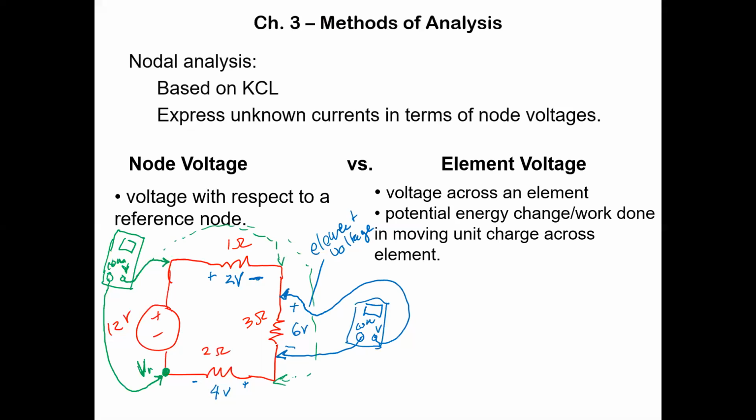We're going to call those node voltages. They give us the voltage, the potential difference, between any point on that circuit relative to our VR node. Our VR node, which is our reference node, is assumed to be 0 volts. It's the reference node, and we're going to see what the node voltages are as we explore that circuit with the red wire of the voltmeter, okay?